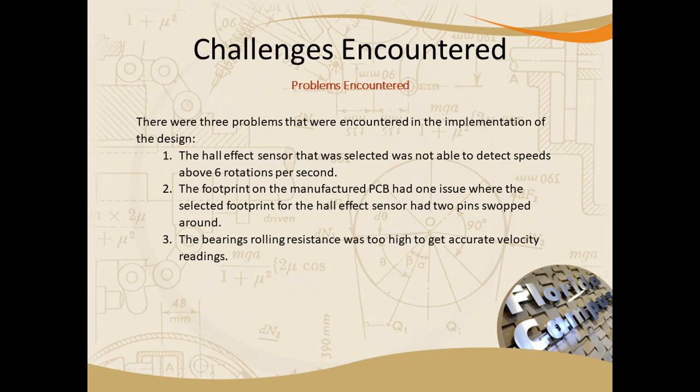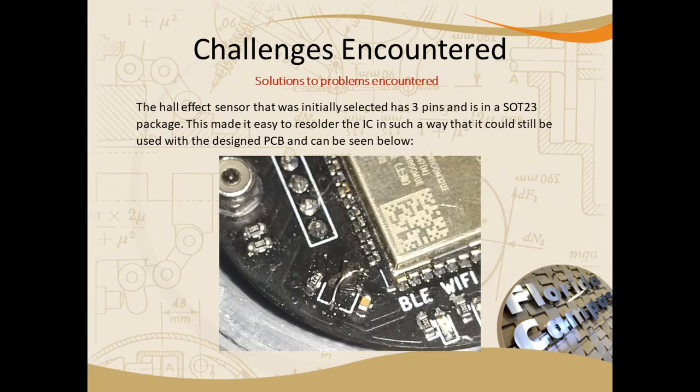Okay, for the problems that I encountered: a big issue with the Hall effect sensors, which I initially thought was a firmware issue, and then later on discovered that the pinout that I had used on the board was swapped around on the SOT23 package. This was resolved by soldering the component on, as you can see in this image.